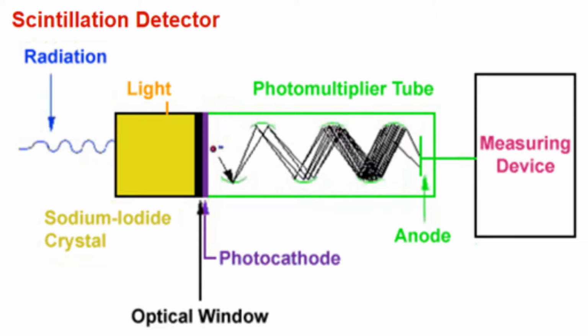These electrons are then pulled towards a series of plates called dynodes through the application of a positive high voltage. When electrons from the photocathode hit the first dynode, several electrons are produced for each initial electron hitting its surface. This bunch of electrons is then pulled towards the next dynode where more electron multiplication occurs. The sequence will continue until the last dynode is reached. This is where the electron pulse is now millions of times larger than it was at the beginning of the tube. At this point, the electrons are collected by an anode at the end of the tube, forming an electronic pulse. The pulse is then detected and displayed by the instrument.